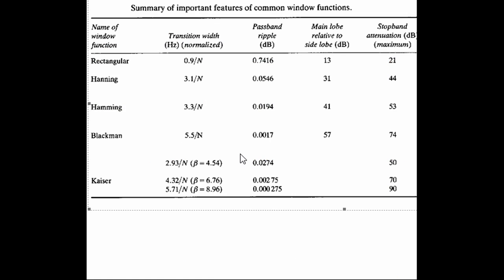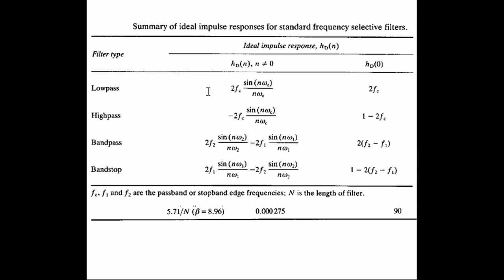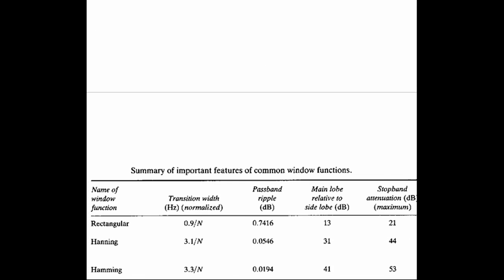The next thing, as I said, we want to do a low pass filter. So on the table, we go to low pass filter, and we get that formula there. We're doing a high pass filter now. A high pass filter, so it means we're going to use these two formulas. So the first value we need to do is the value for 0, and then we're going to do the value for 1, and then the value for 2, and then up until 13. There is a shortcut. I'm going to show you the shortcut, but for now, the first value is 0, then the next one is 1. So the first value is 0, meaning we use this formula, not that one. That's for 1 and on. This one is for the first one, 0, 1 minus 2 FC. There we go, 1 minus 2 FC.